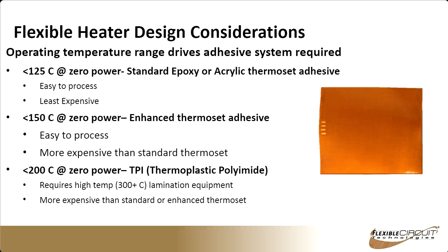Hey, Mark, a question came in. Why are they only suitable for static applications? Well, the issue that we have with flex circuits in general is that when they heat up, the adhesives will tend to soften, and you're going to lose some of your bond strength. And if it's heated and moving at the same time, you can actually have delamination problems.